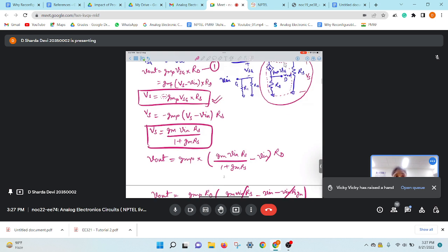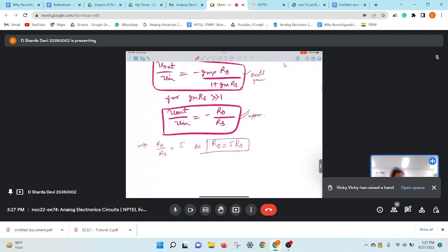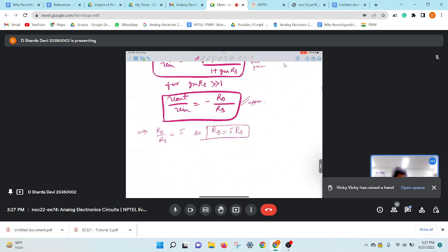Ma'am, I got two equations, but I cannot find the values of the resistances from them. Can you let us all know what expressions you got? From the first condition, R1 plus R2 is 10 megaohms, and from the MOSFET current equation, ID is equal to K (VSG minus VT) squared. I got the source to gate voltage VSG equal to 0.679 volts, and we can use that equation.